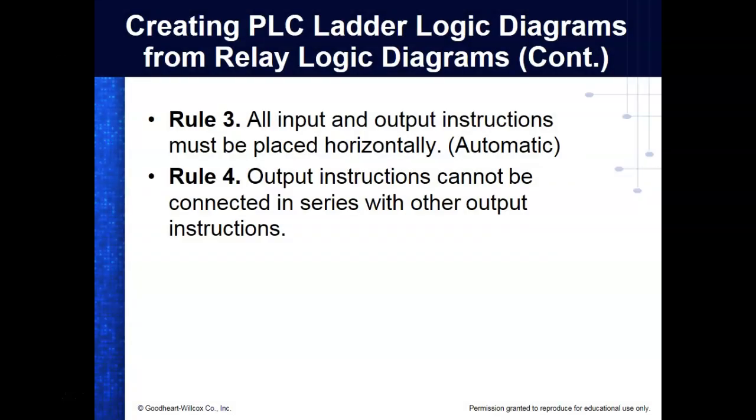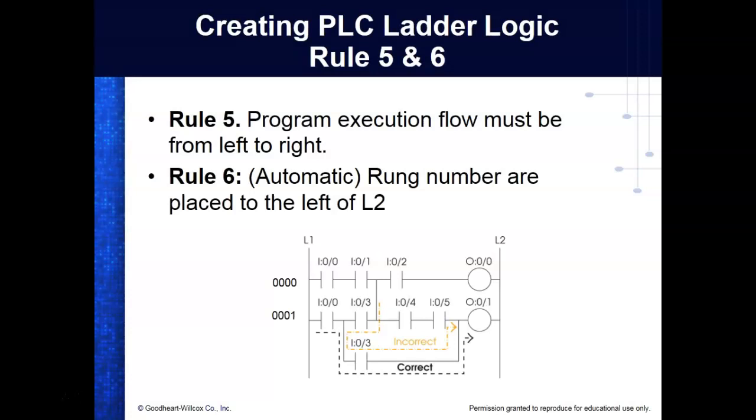And this is automatic. Output instructions cannot be placed in series with other instructions. Everybody okay? Other output instructions. Y'all understand that? Program execution flow must be from right to left.